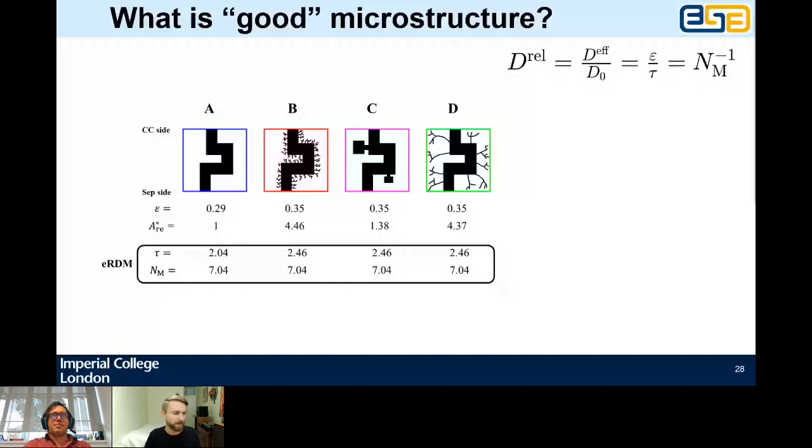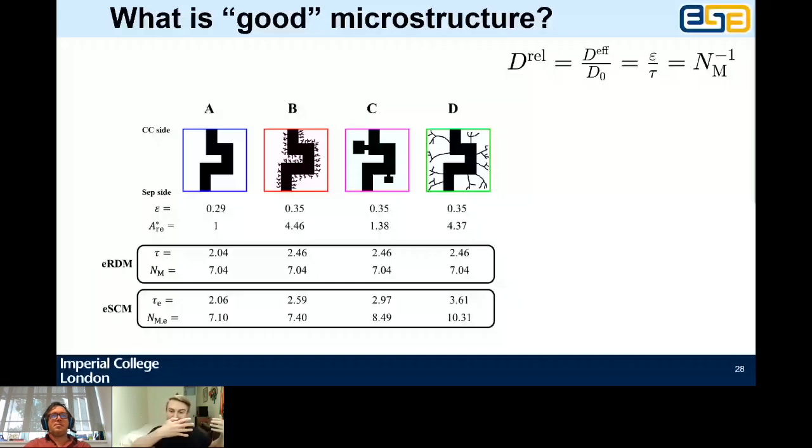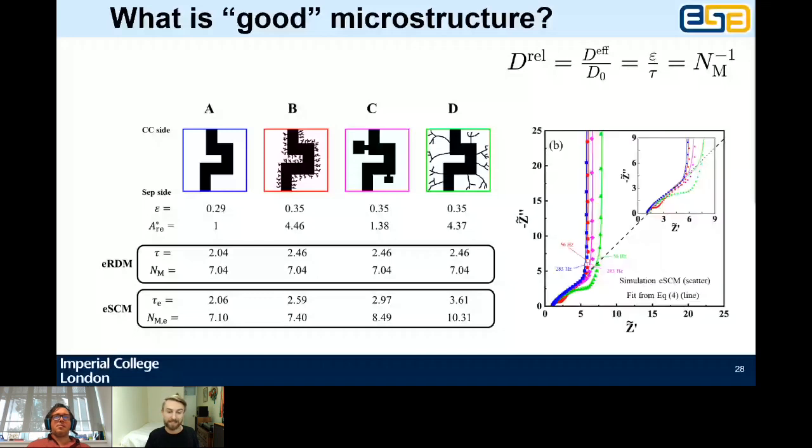So that's problematic. If you use this frequency domain response, where you're trying to get in and out of pores at either side of a symmetrical cell, they now have quite different numbers. And clearly some are much better suited to being a battery than others. And I'll come back to which ones we believe that is in a 3D representation of that. But again, our numerical approach, which is what Tu and I developed together, gives you a full impedance spectra of this behavior.